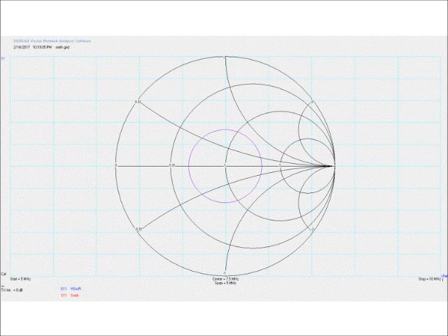So if you find that your SWR falls anywhere in this part of the circle, the antenna is what's called a little short. It's called capacitive reactive. If it's up in this part of the circle, it's a little bit long. It's inductive reactive.